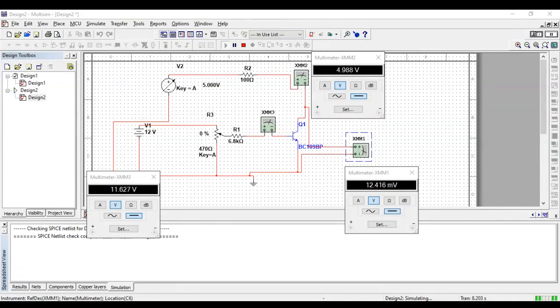So now we have the collector voltage fixed at 12 volt, and now we are changing the VCE from 0 to 3. Okay. So we keep IB constant, IB is nothing but the base current. Now how do we keep the base current constant? With the help of this potentiometer.